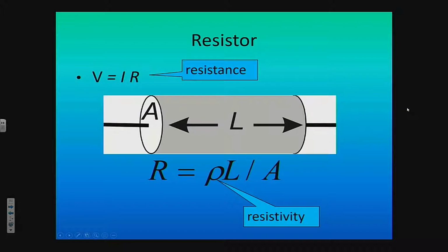So resistivity, you're probably all familiar with Ohm's law, V equals IR. We're actually not looking at resistance, we're looking at resistivity, which the symbol rho represents, because it's what's called an intrinsic rock or soil property. That means it doesn't depend on how it's measured. Resistance does.